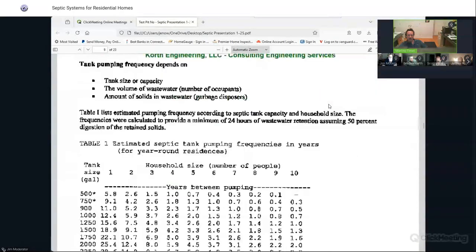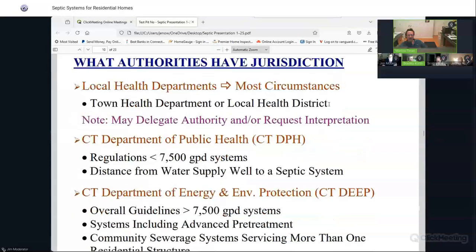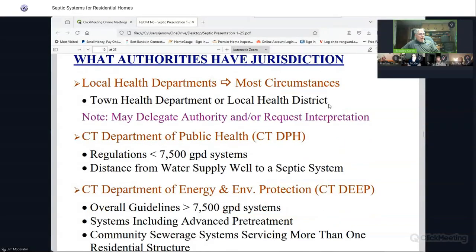Yeah, I mean, you get that. And the other common way of degradation that you would ask about is the backflow from water softening systems, which a lot of times use salt. And of course, what does salt do to concrete? I'm sure that people already know what it does over time. And that's why they don't allow the backwash, but that regulation hasn't been in effect for too many years. So if you have an older tank, they may have been putting backwash in there for quite a number of years. Something to look for.